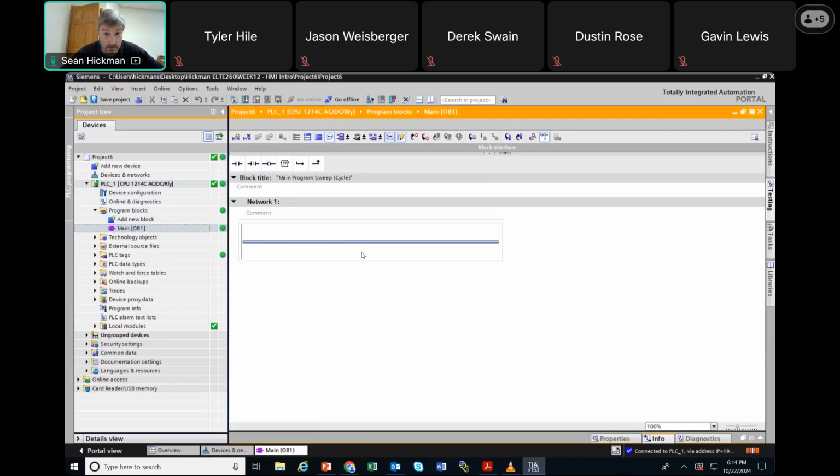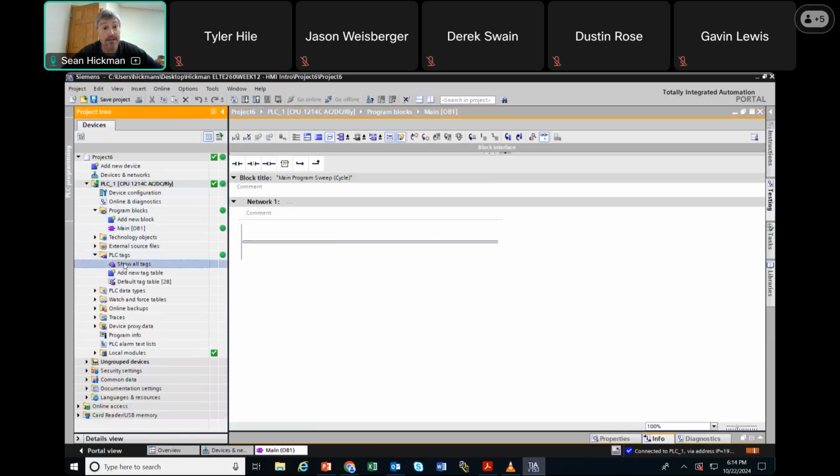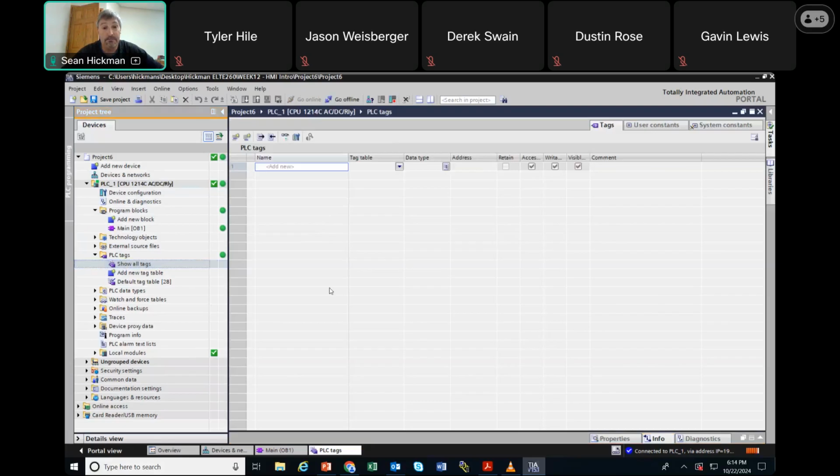Another popular selection over here is going to be PLC tags, okay? So once again, when I show all tags, it's going to pop up like this for my tags. Now, what's cool about this is it's pretty smart. So I'm going to make a tag name right here, and I'm going to call it switch 1, and I'm going to click enter, and notice it made it I 0.0.